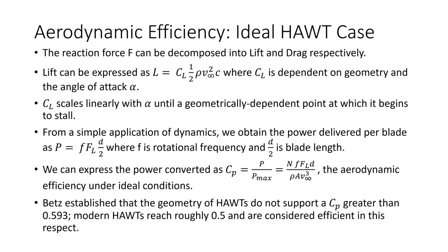That reaction force F shown on the previous slide can be decomposed into lift and drag. Our lift is driving the system. We have it characterized there. And from that and some applied dynamics to a uniform rotation, we can figure out the power and then relate that to our previous available power as a coefficient of power, or the converted power, which is our aerodynamic efficiency under ideal conditions.